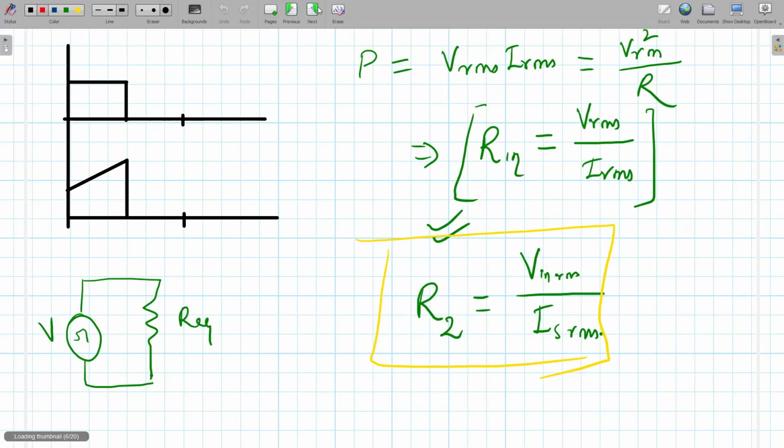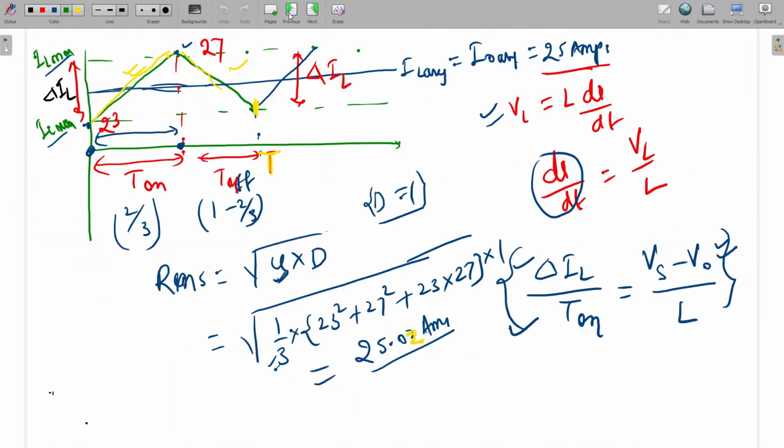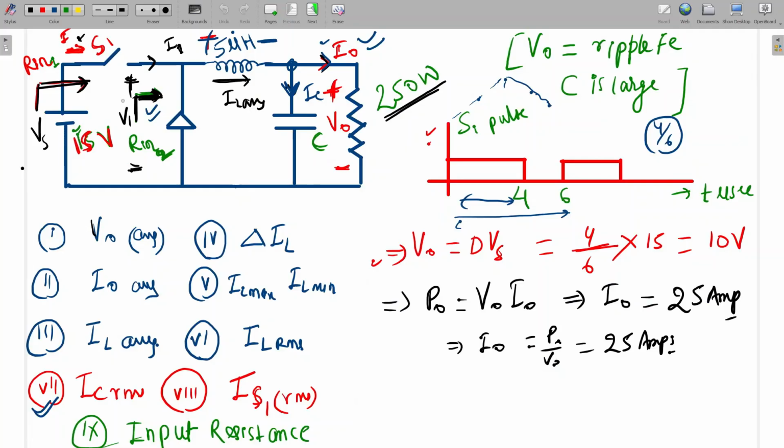One second. Like here I have drawn the source current. What will be the voltage here? First I will go here. Here the voltage will not be constant, it will be a periodic voltage from here to here. This is V1 and this is I1. I1 is present when the source conducts, so the switch will conduct for the duty, and in the next cycle this diode will conduct. So the voltage here will be variable. For on time it will be present, and for off time this diode will be shorted, so the voltage here will be 0.